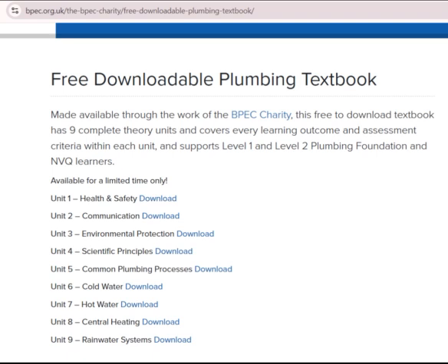Modern boilers must be the energy-saving condensing type boiler, which has been designed to extract as much of the generated heat out of the combustion of gas and oil as possible. C. Heating systems incorporating a combination, combi, boiler. These are probably the easiest of all heating systems in terms of design and installation. Heating systems that incorporate a combination boiler simply require flow and return pipework to and from the boiler.